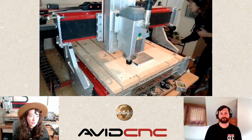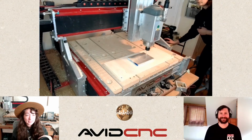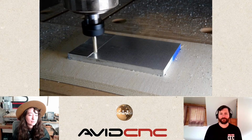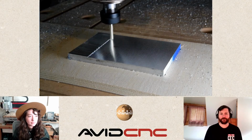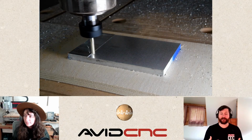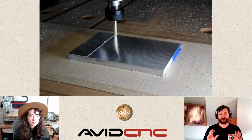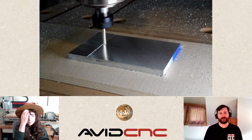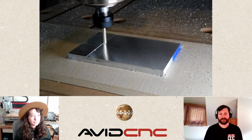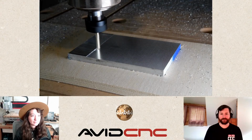And we're going to start out with our leveling. Ooh, I got some bright sun coming in here. Surfacing, yeah. So look at that surface finish there, and phenomenal chip evacuation. If you wanted to use any compressed air, I also have used wedges of different sorts and just blowing that air into a wedge for collecting the chips. That works really well to try to keep your floor as clean as possible. Yeah, this looks really nice.